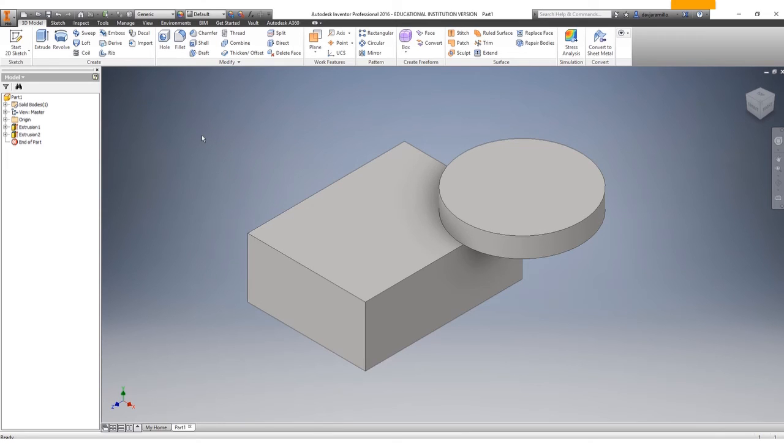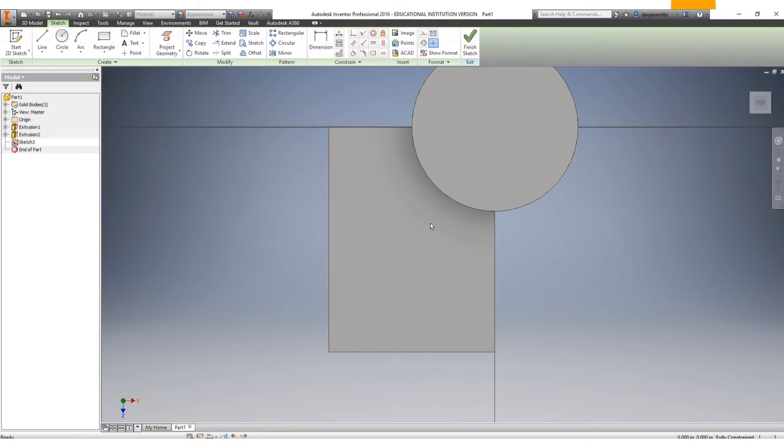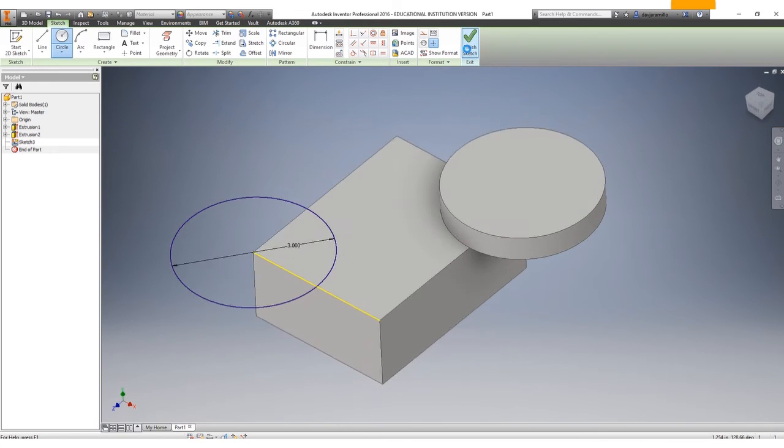So I'm going to go ahead, I want to do one more sketch and then I'll walk around and see where we're at. But once you've done this circle, create a new sketch on top, just like the other one was. We're going to click the top again. We're going to do a 3-inch circle again here on the bottom corner. And then I finish my sketch.